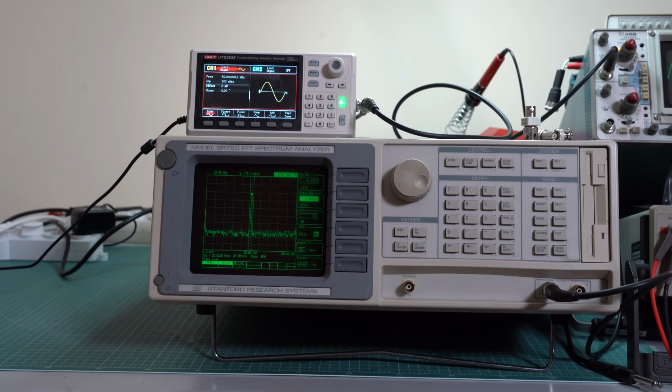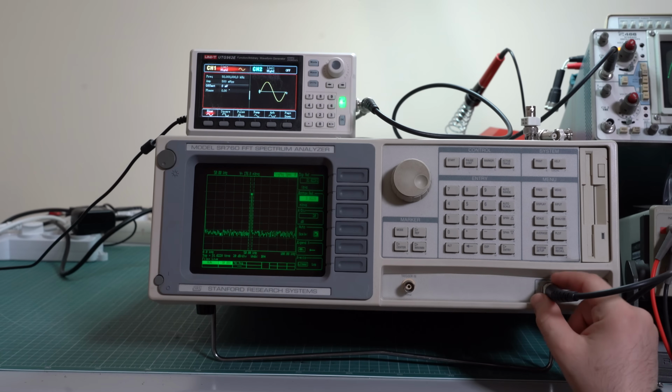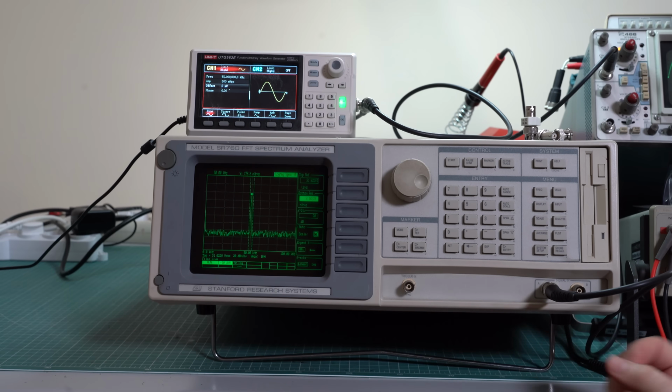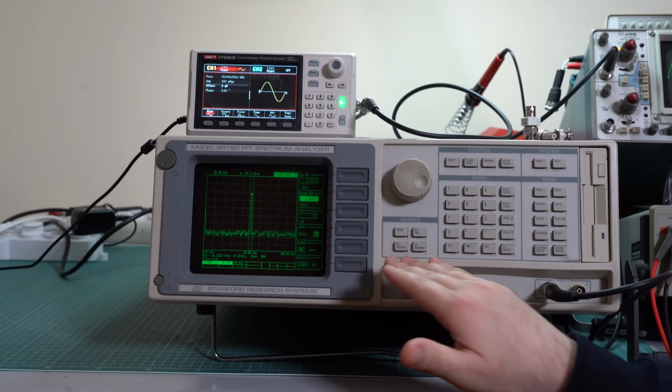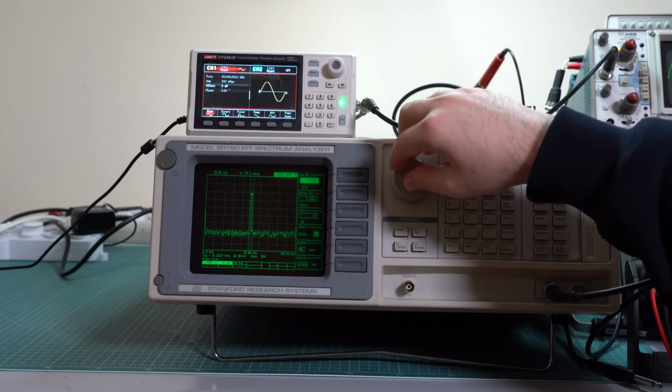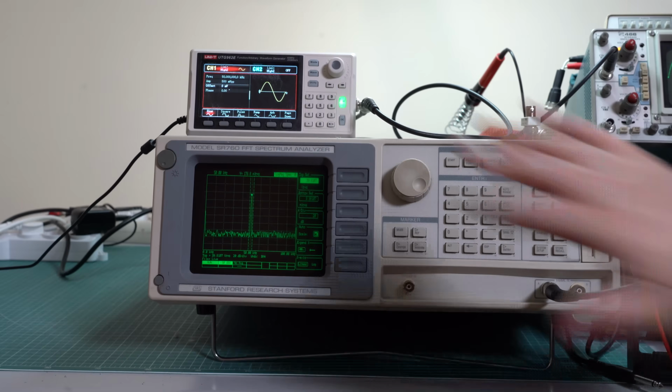So to sum things up, make sure that the input signal doesn't exceed the maximum supported by this instrument. Start with a large range and work from there, and then you have to set the range so that the front end doesn't distort, and then you can also set the scale in dB per division so that your signal looks basically as high as you wanted it to be. And then, just like you would on the oscilloscope, you can also offset the signal up and down, and this is what the top reference and bottom reference settings are for.